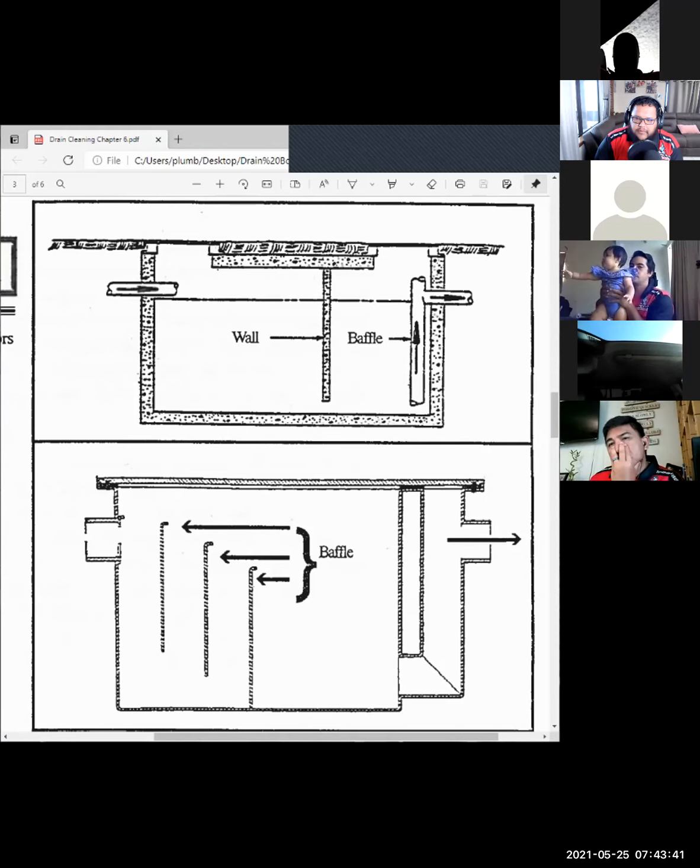Yeah, one more thing. When we're looking at these grease traps, we've been in some situations where guys come back and tell restaurants, "Oh, your grease trap is full," when it isn't necessarily full. We talked about this in our septic classes: the water level is at or below the inlet pipe, so it's always going to be full of water.